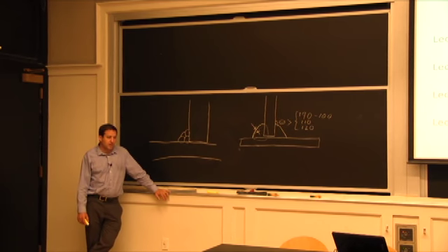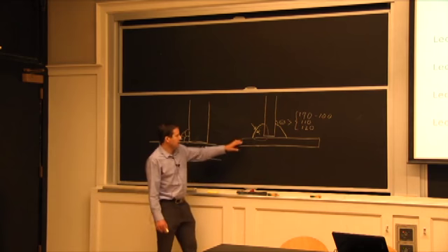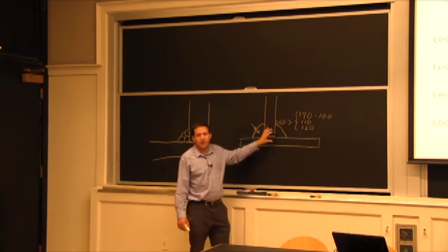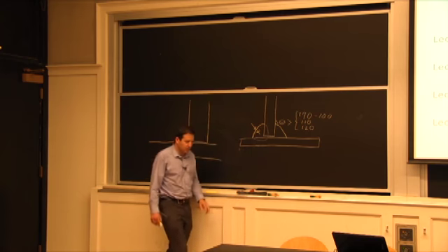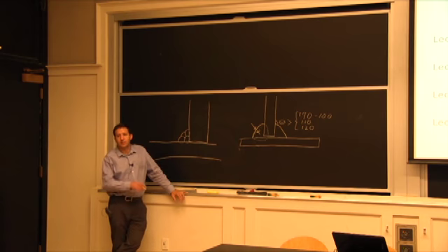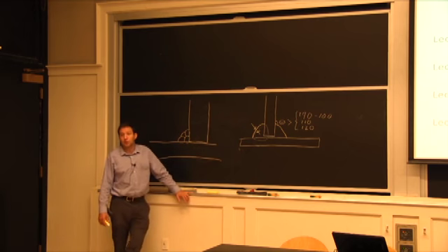The AWS is the only one that you don't have to qualify a single weld. If you say I want this very typical type of welding detail, as long as you have a qualified welder and a material that is listed in AWS, you can go and weld it. So that's a big advantage as opposed to the other codes. They will require you, even though your joint is very simple, to do your own qualification.